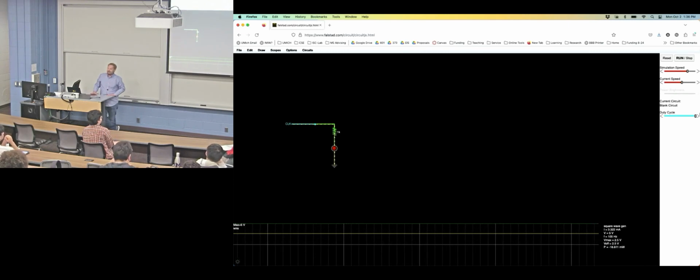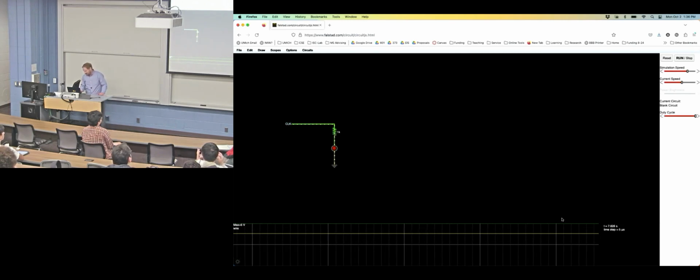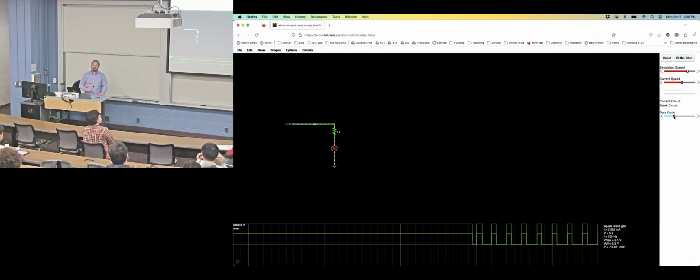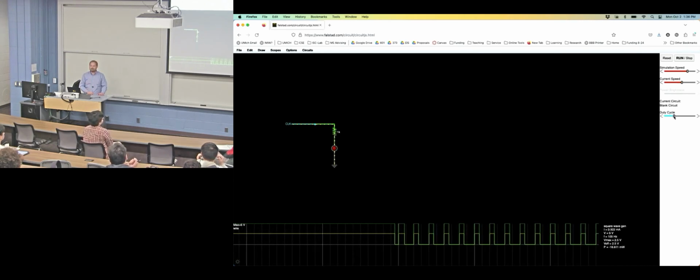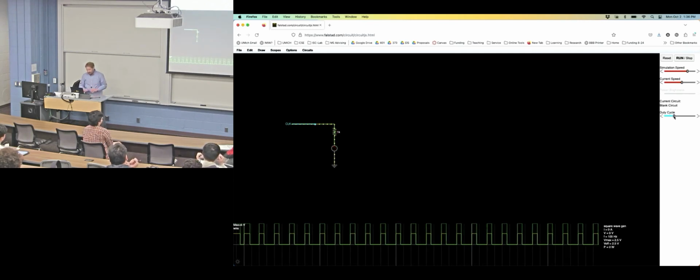Okay, so you may not believe it, but this is actually important and useful. Dimming lights, controlling motors, you guys are going to be using it to control servos. Servos are a type of motor that don't spin continuously. They have a basic little arm that will move usually between 0 and 180 degrees, and you encode the position of where you want that thing to go as a pulse in time. So you set your pulse width to, I don't know, 10%, and it would go 10% of the way there and hold that little arm there. Has anybody seen a servo before? Fantastic.